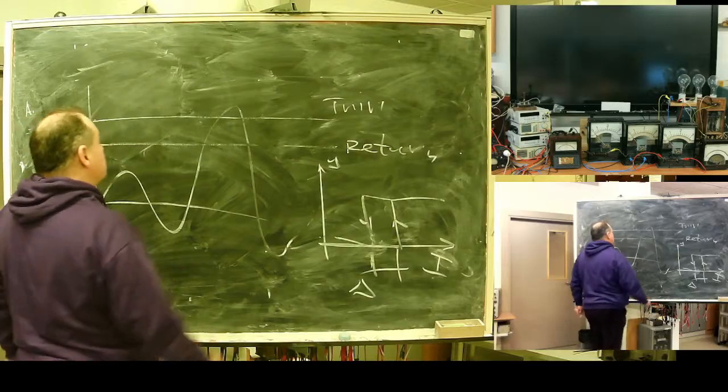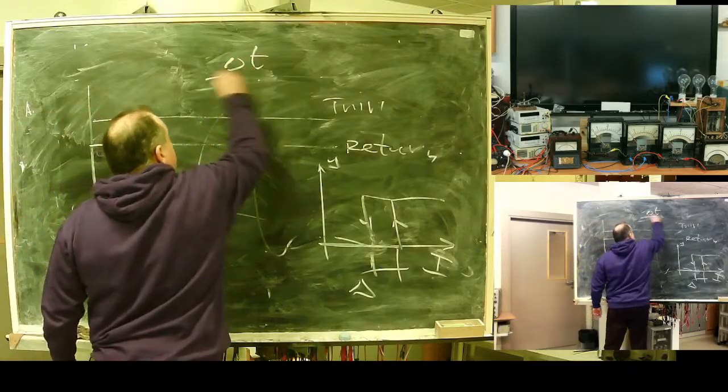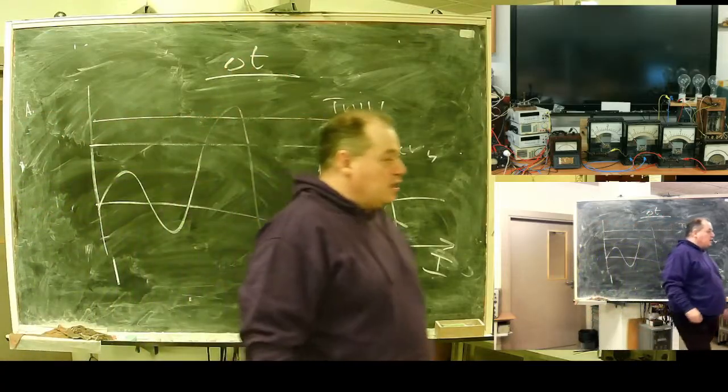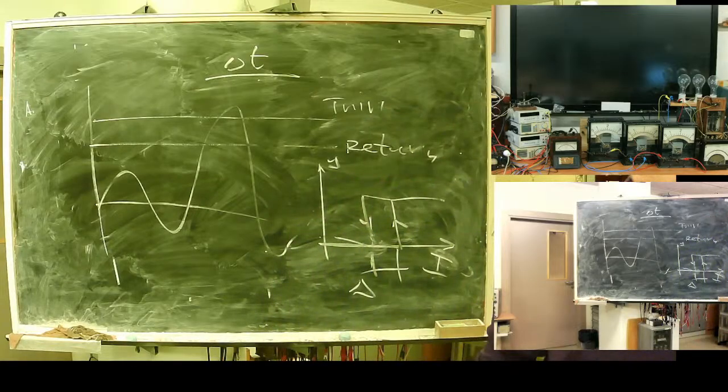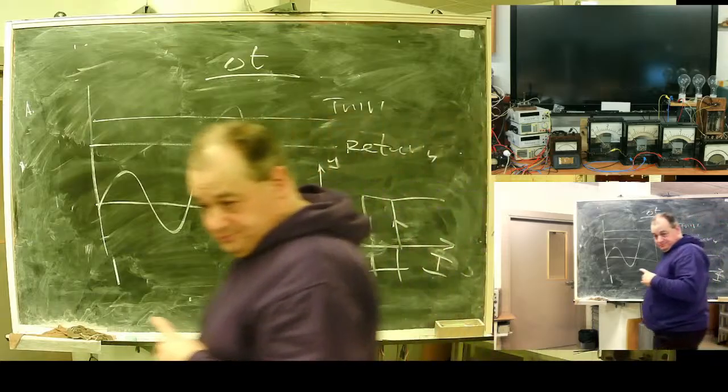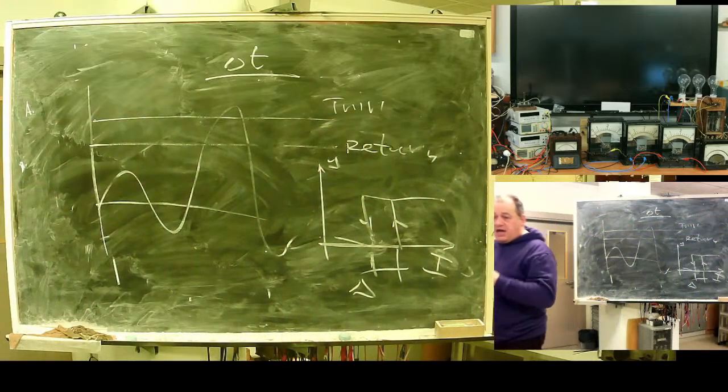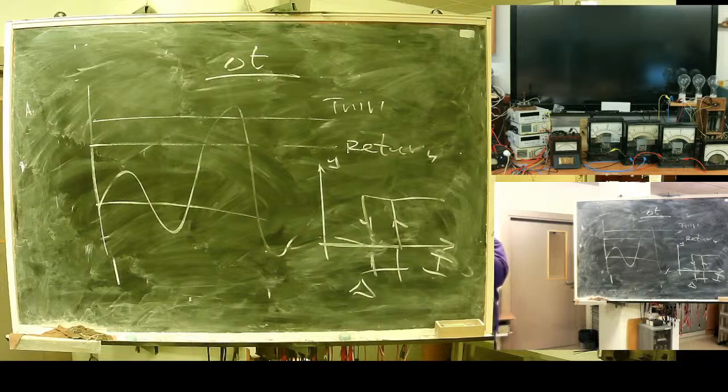And what else? I should not disconnect if it was a short spike, some kind of short glitch. Understand? Averaging saves me from glitches. Not 100%, but it's a well-working protection against short glitches, which may be transients, computation transients, or lightning, something like this.